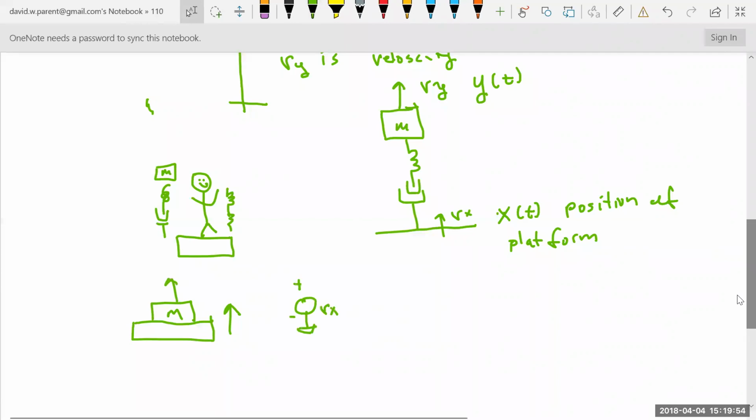I'd have Vx, the voltage across the capacitor, equal to the velocity Vy. And you might say, well, there'll be current flow. Yes, but an ideal voltage source can make that current be whatever you want it to be to make the voltages equal. And so there is no damping. Nothing happens.